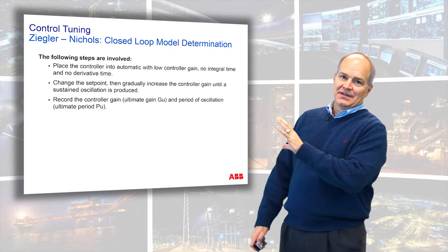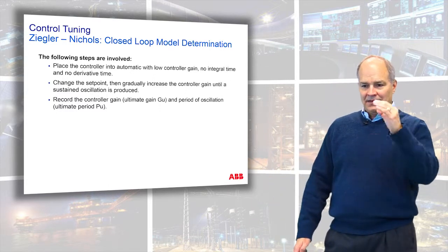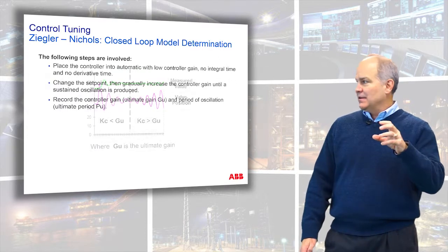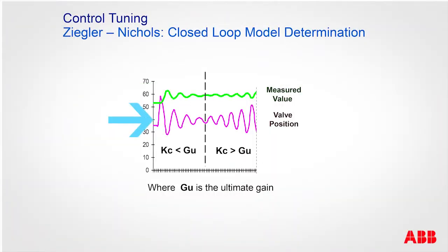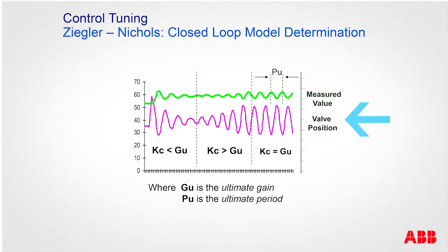There's a couple of different steps that they've modified, and it's called the ultimate gain method, where you set the integral to 0, you cause a disturbance, well, here's the picture, and you start adjusting the gain until you get a sustainable oscillation. When I've tried to do this, I pick a gain, I change the set point.